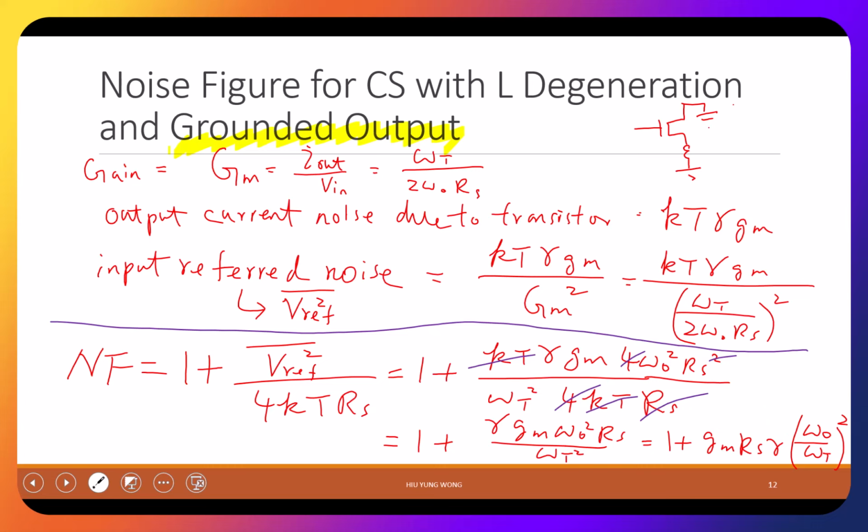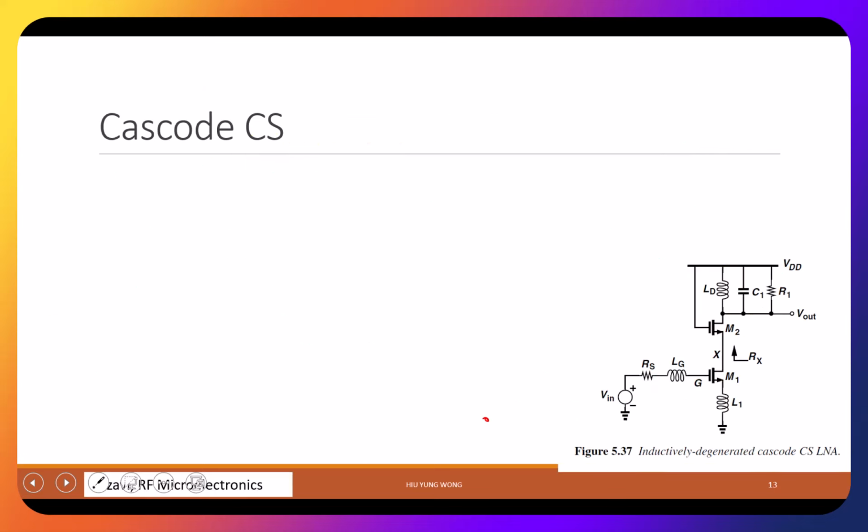So what is the noise figure of this whole thing? Almost equal to 1. Right? This is the first time we see something way lower than 3 dB. But of course, we're only talking about the first stage, right? But at least this looks promising, right? So now, then we continue. We have this noise figure is about 1, and then we look up, right?